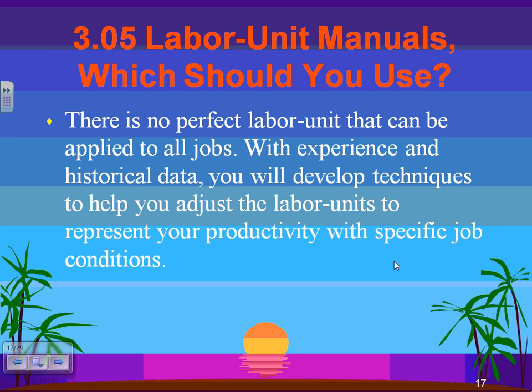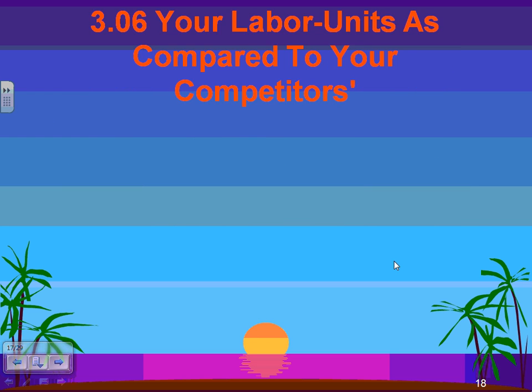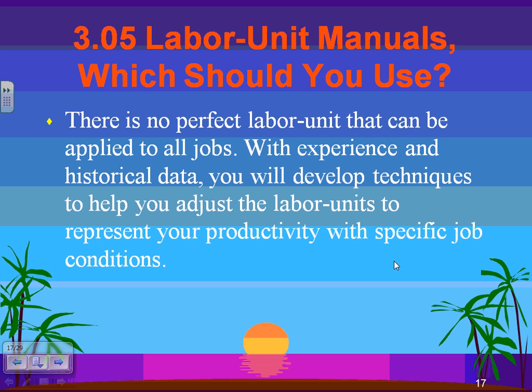Which labor unit should you use? A lot of people, guys, if you're a union shop right now, use NECA and modify it. The best labor unit that you can use is your own. So what a lot of people do, guys, is take these labor units and adjust them to your own company based on the productivity, the supervision, and the management skills that you have at your company.